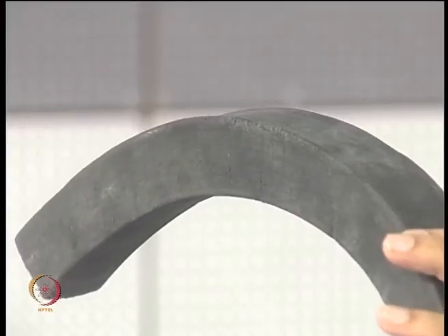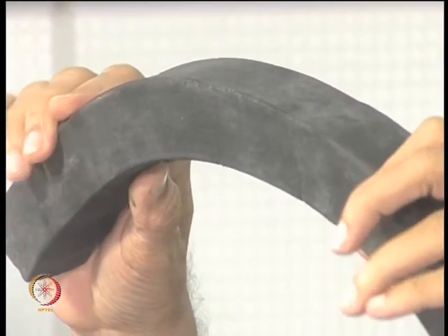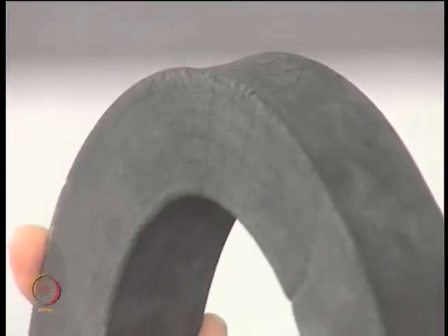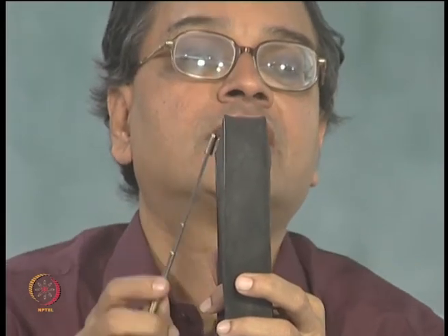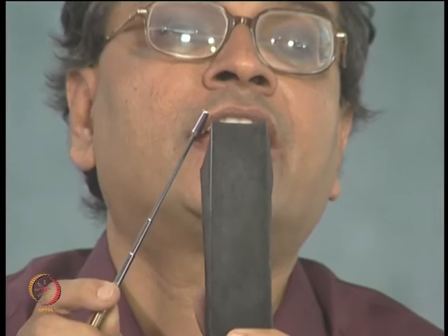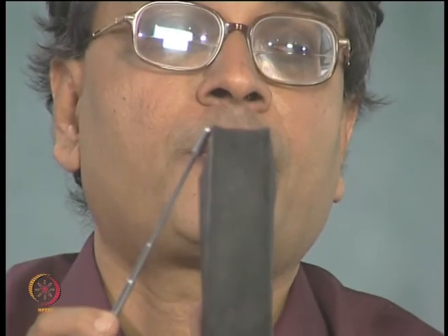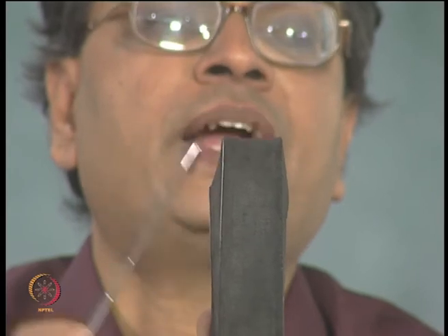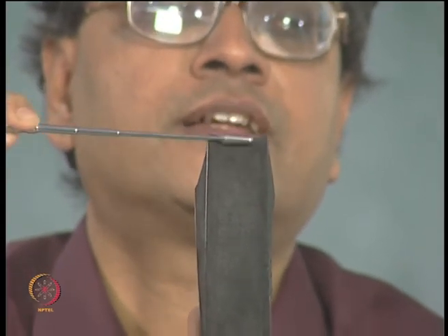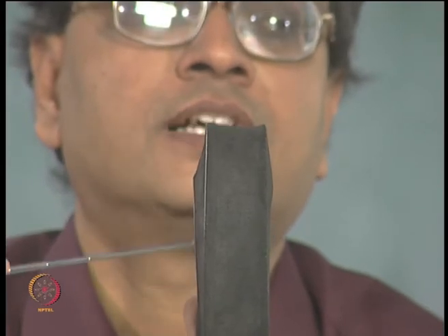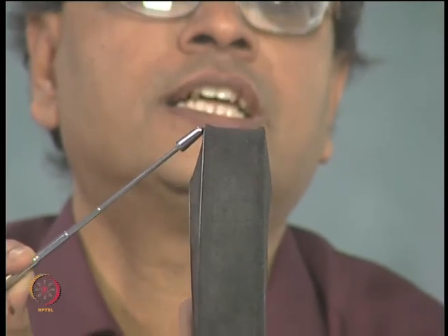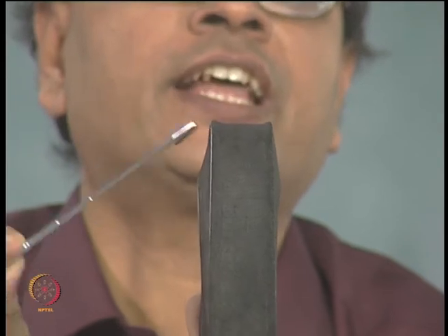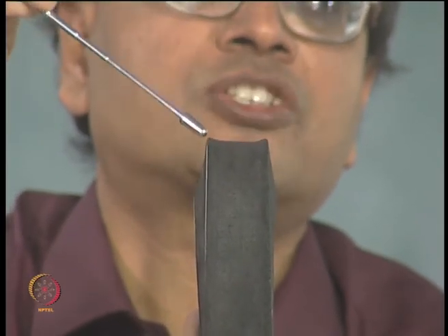I have said that in addition to this you also have strain because of the Poisson effect, and what you find is if you look at it sideways, I have a bulge at the bottom and it is not bulging out in the top. Why has this happened? In the way I have bent, this fiber is subjected to tension and the inner fiber is subjected to compression, and because of the Poisson effect, the bottom portion bulges out and the top portion narrows down. And you also see one more interesting thing: you have additional curvature here because of this, and